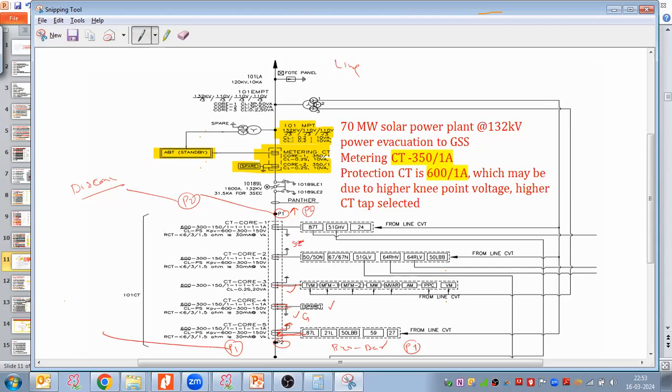Sorry, in that case P1 here, so S1 would be here, S2 would be here. But yeah, the star point I'm making towards the protective equipment. So the protective equipment is the line, so the star point is towards the line here. Here, this is for the transformer. T70 is the transformer. This was line coming, trafo way. So due to that reason, bus not coming, trafo coming here. So the star point I'm making towards the transformer here. Okay, this is what we discussed for polarity, that I just extended that discussion for this SLD extract.